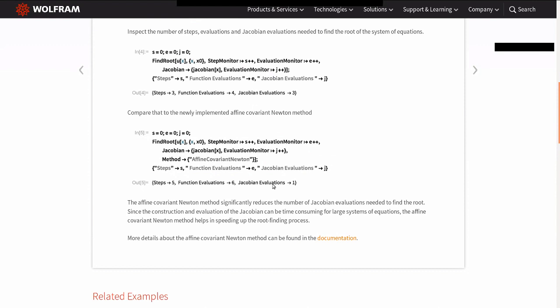This algorithm also has something called Broyden updates. So it actually understands how good the Jacobian is as an approximation to the system, and it tries to reuse an old Jacobian as long as it can. So it keeps track of how good it is. And if it finds the old Jacobian I'm using is no longer applicable, then it computes a new one. But if it can use the outdated Jacobian, it will use it for as long as it can, and thus try to again minimize the number of times the Jacobian has to be set up and evaluated.